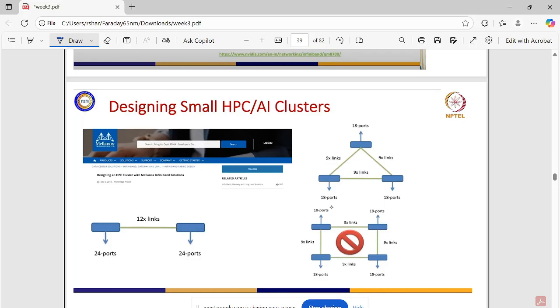So it is not like a single switch. It is actually a big device which contains multiple ASICs inside, and they are connected to each other in a certain way. For a single ASIC, there is a limitation to how big an ASIC you can make. One of the simplest limits is the die size. You take a large wafer, and to get a good yield, you will have a certain size of die on it. That certain size of die will be able to service only a certain number of ports.